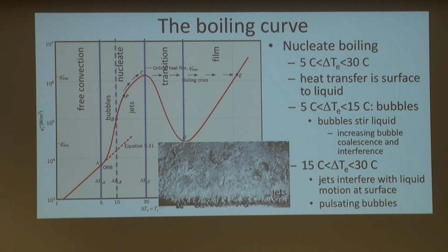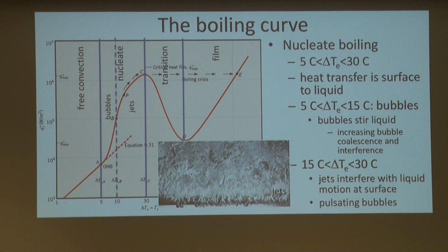And so far, the best way of cooling these semiconductor lasers is you put in the back a heat sink, and you cool it in this regime of evaporation. You just shoot it with water that evaporates. That is the fastest cooling you can have. You don't have cooling channels. You don't have fans. You don't have any of that. You're just shooting it with this thing, right? Very interesting. You got to know what you're doing, right?